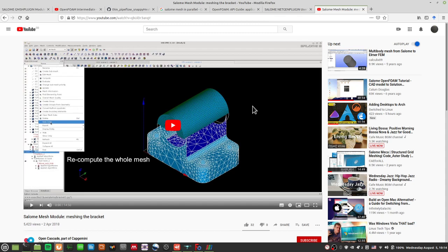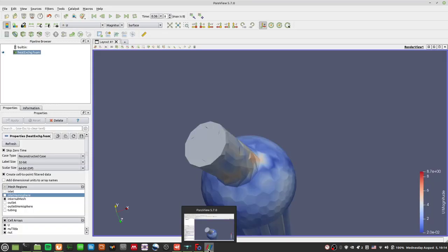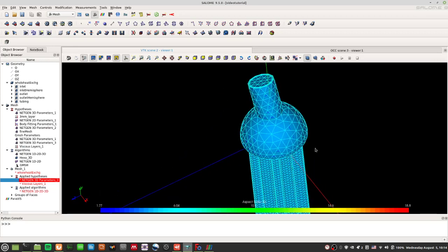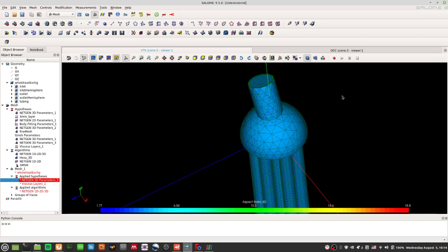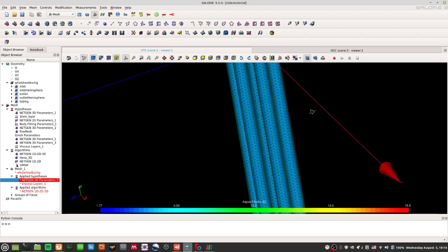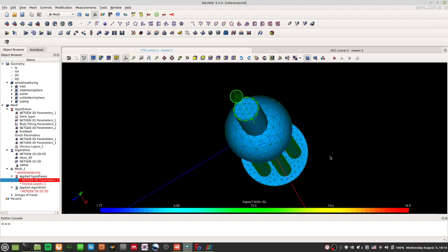But what I've showed you is to roughly work with Salome. Know how to get around with Salome, know how to do tetrahedral mesh, know how to do boundary layer addition. Of course, getting the simulation stable is a whole another ball game altogether, and that actually takes a lot more experimentation and fine tuning. So you got to play around with the mesh. You have to troubleshoot, but that's the name of the game when it comes to CFD. There's no running around with it. You can't run away from these problems. You have to solve it on your own.